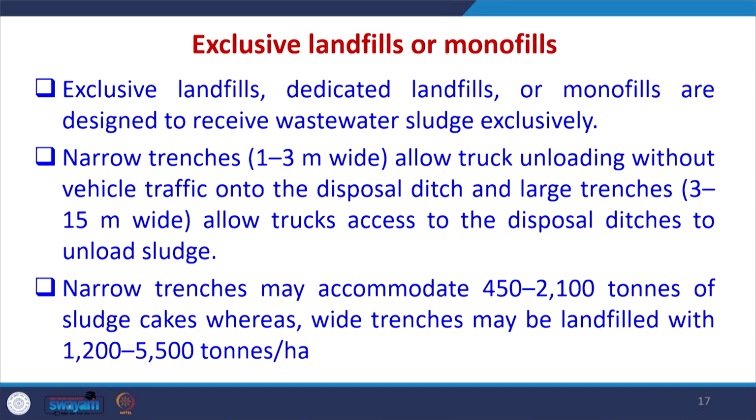The exclusive landfills or dedicated landfills or monofills are designed to receive wastewater sludge exclusively. Narrow trenches 1 to 3 meter wide allow truck unloading without vehicle traffic onto the disposal ditch, and large trenches, more than 3 to 15 meter, allow access to the disposal ditches to unload the sludge. So, we have to take care whether narrow trenches or large trenches are there. So, we have to design.